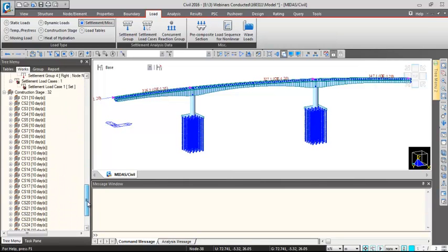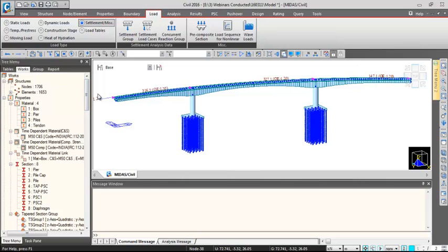Now one of the important parts in basically our structural engineering, what it allows us to do is the superposition of the different static load cases, right? So there would be certain bending moment due to moving load, there would be certain bending moment due to dead load, and there is going to be certain different bending moment due to settlement. Okay, so when we are giving the settlement, the other load cases, your moving load, your dead load, all of these also would be affected due to the moment redistribution happening due to the settlement.